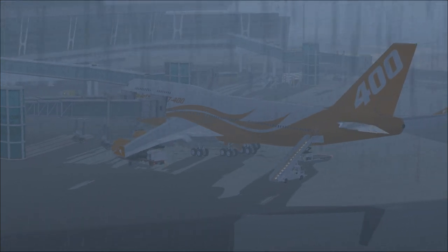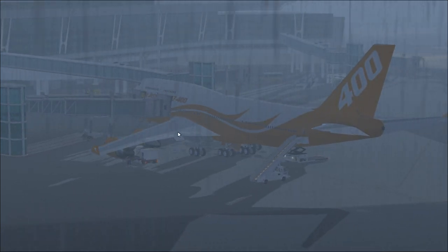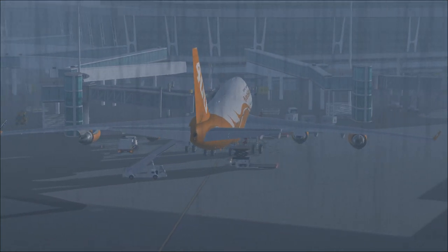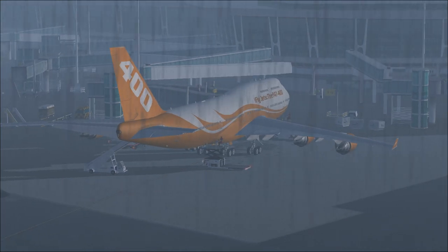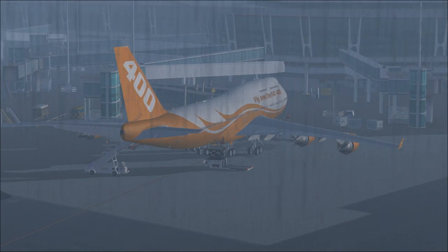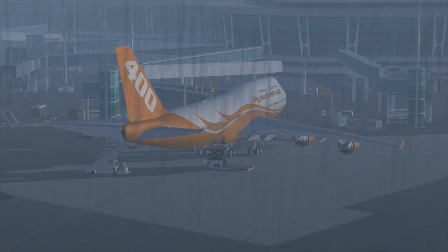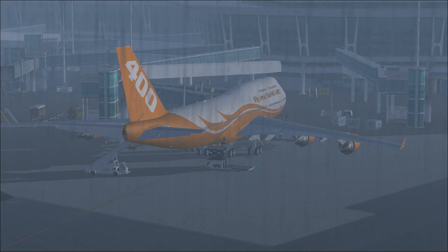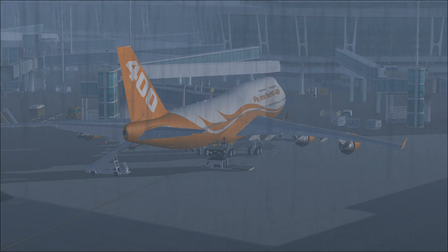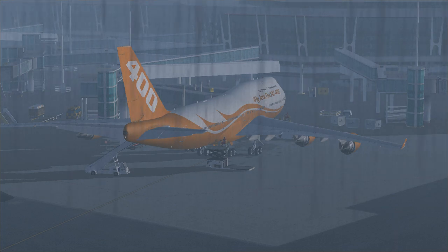The control group, as you can see, the elevator and the inboard aileron are actually dropped at this moment because the hydraulic system of the 747 is very, very complex. We have 4 different systems. They are driven by 4 different independent engines, of course, and every single surface has its independent source, so you can move any surface with a specific hydraulic system. If you have a failure on a hydraulic system, you will not lose any flight controls, but if you lose 2 hydraulic systems, you will lose some components.